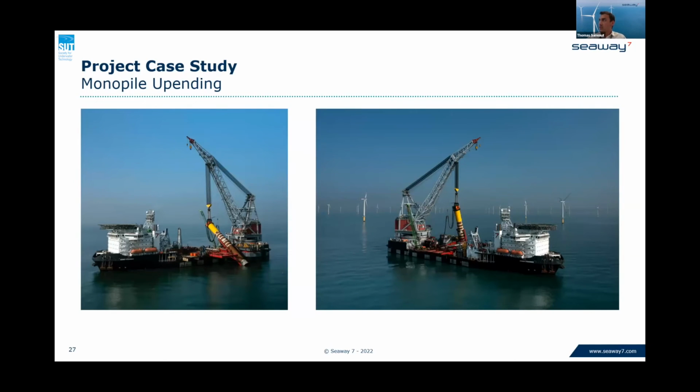Worth mentioning that this tool you see here is another sort of technological advancement in that we don't need to swap around tools. We can upend and vibrate down the pile without changing over equipment. And it's very neat in that it can support now these larger monopiles. Initially, this technology was used on pin piles and smaller piles, but now it's coming up to the larger foundations as well.